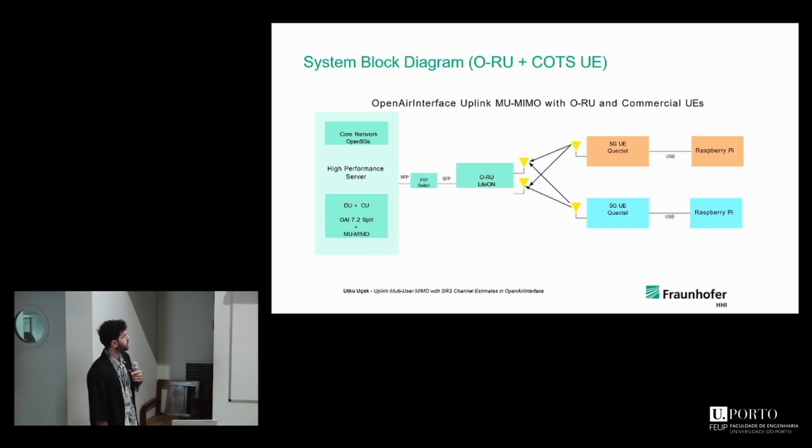Since then, we implemented a comb-based SRS scheduling where the users get the channel from the same OFDM symbol. This also improved the stability in the USRP-based system, so I expect it also improved it in the ORAN-based system, but we did not test this yet.